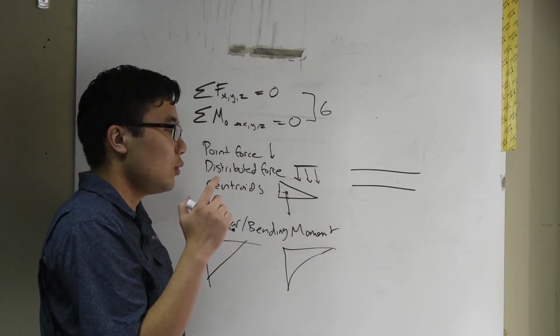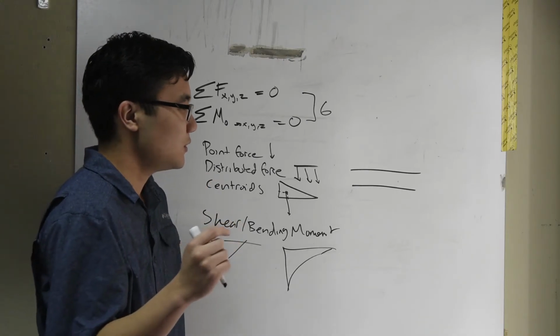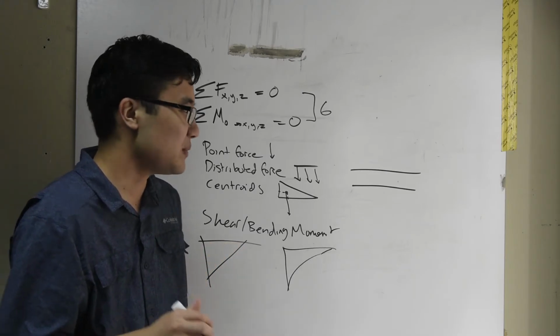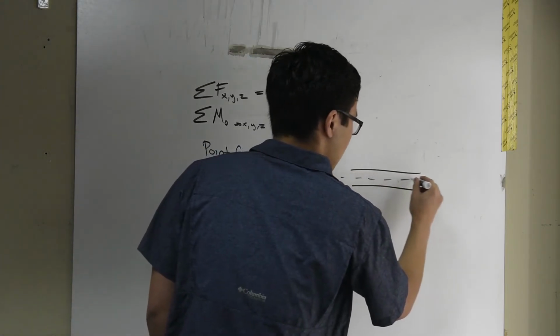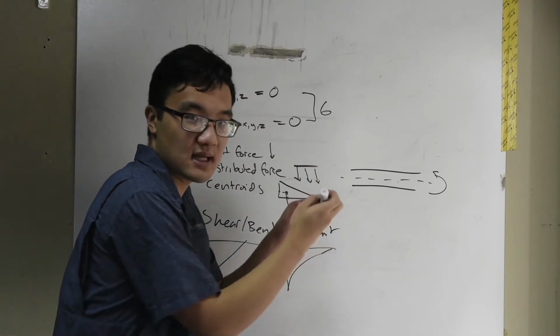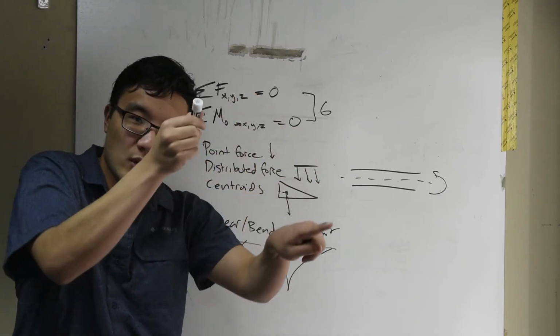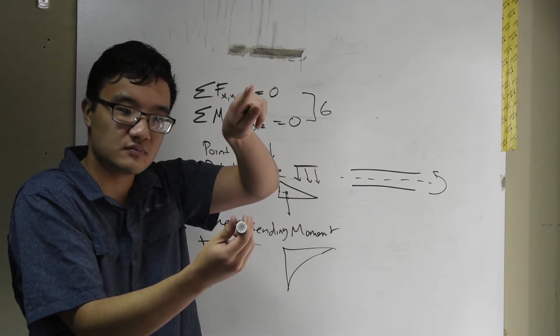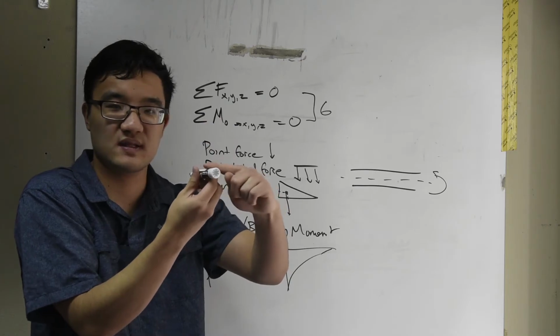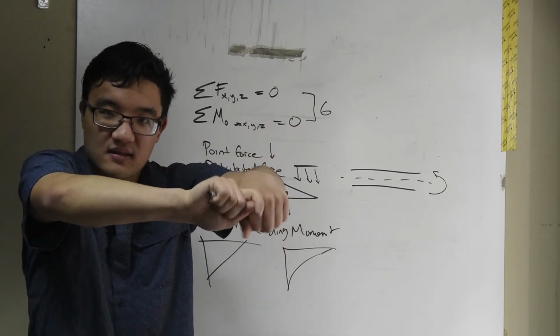Now, obviously you guys know we had 2 bars going to the tail, but why? Well, because of any sort of moment about this axis, right? About the axis, so let's say that the tail is coming out of the page like this. Here are the 2 rods, right here. Any sort of twisting in this direction, if I just have 1 bar, has to be resisted by the torque. So the bar actually physically has to resist this torque.